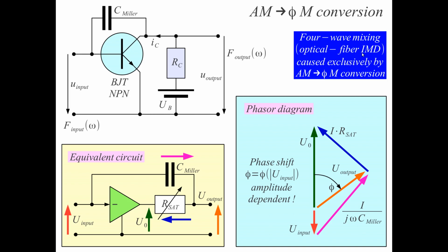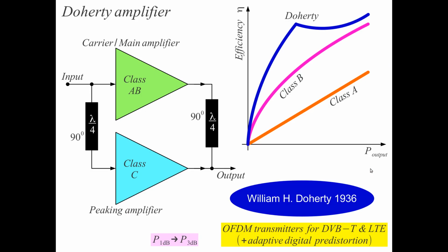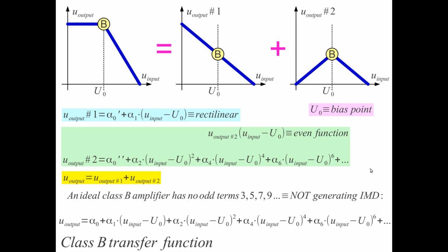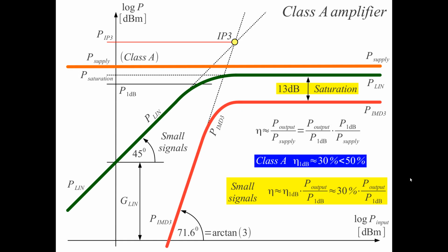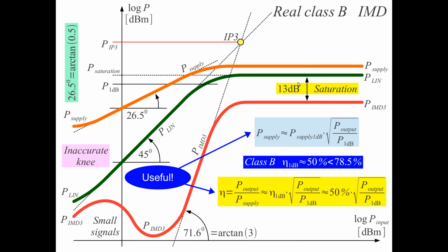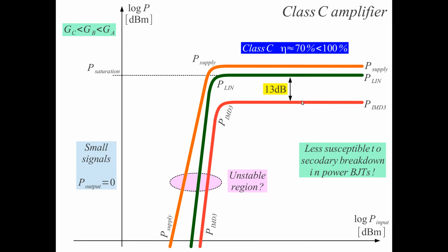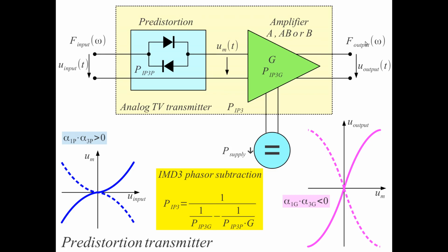So this is yet another source of distortion, and we didn't discuss this source of distortion here with saturation. Talking about saturation here, we only considered the in-phase saturation, so just limiting the signal amplitude. Besides the amplitude, also the phase is a function of the driving signal power. So even here or here, we also have other sources of IMD. Well, a Class C amplifier is usually used at its maximum output power.